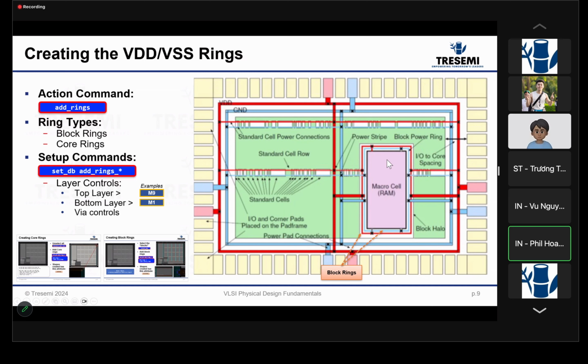You want to tell the tool what the top layer and the bottom layer are. This has something to do with the fact that if you have metal 9 and you go over some structure, you see a cross section connecting all the way to metal 1. But if you do a metal 4 here, then it will see a cross section of metal 1, it won't veer down.